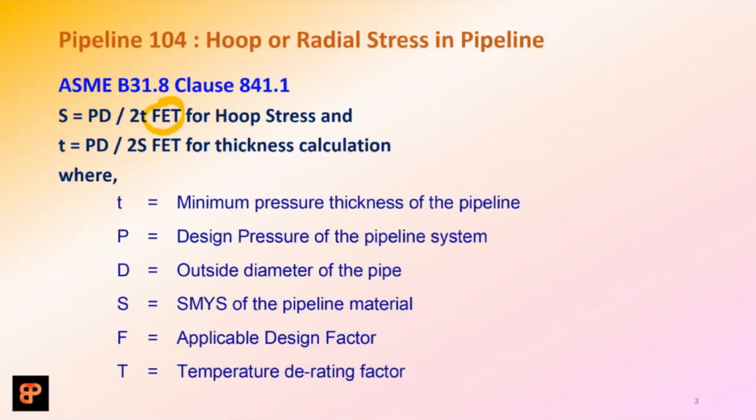It's very important. E is the joint efficiency. In this case, our code provides joint efficiency as 1 if we are manufacturing the pipe in a certain way. And for the oil and gas industry, the pipe manufacturing and its welding and NDT techniques are very strictly followed. Therefore, our joint efficiency is always 1 for oil and gas pipeline systems. Yeah, oil and gas pipes basically.